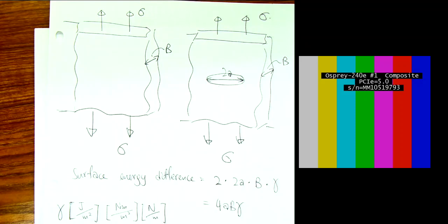So that is one of the difficulties in Inglis's solution, and therefore that's where we started looking at Griffith. Griffith started looking at the problem and tried to get around that issue at the crack tip, and instead of trying to directly calculate the stress at the crack tip, he used an energy balance approach, right? And that's what we were talking about last lecture, right?